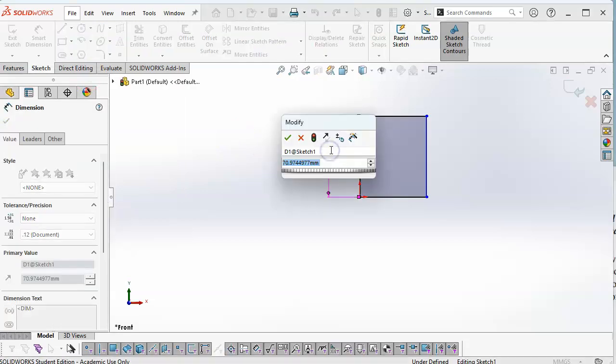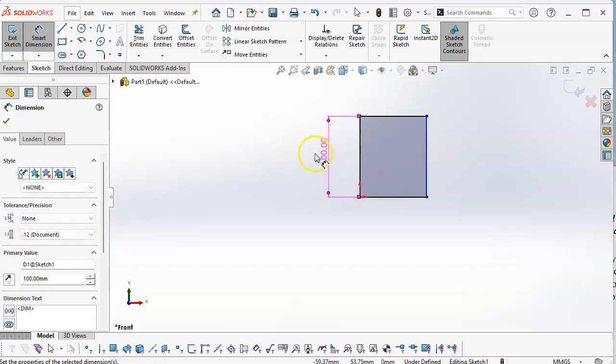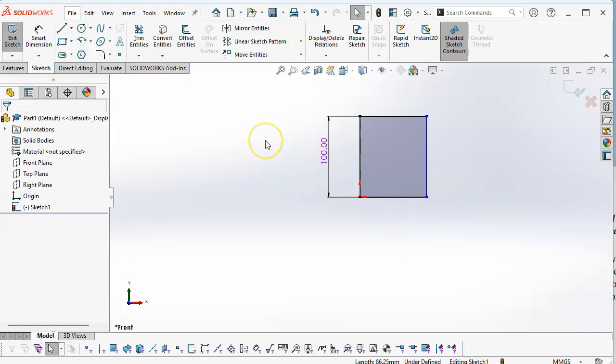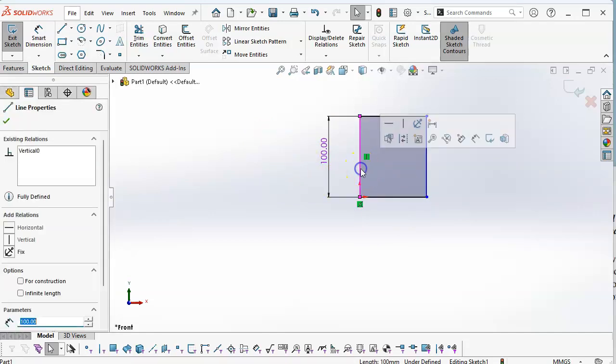and since we're in metric, we'll go 100 millimeters, and then the choice is to put another dimension or set a relation. So if I want a dimension, I'm just going to click and click again, set the number, but I'm going to escape out of this, escape one more time to get out of the dimension, and then we do the select, control, select.